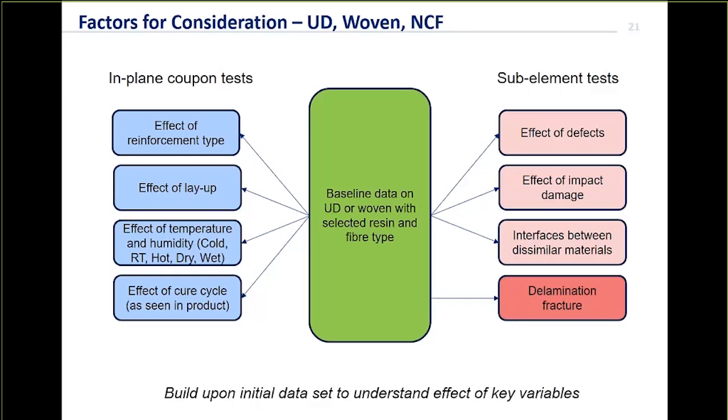You have to consider the condition that you're testing in, the temperature and humidity levels and moisture content of the composite can have a big effect on the properties. So if you're wanting to simulate in particular conditions, then you need to make sure that you're covering that.